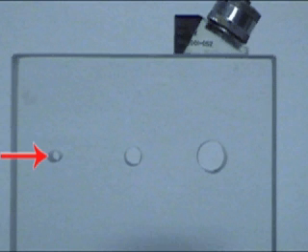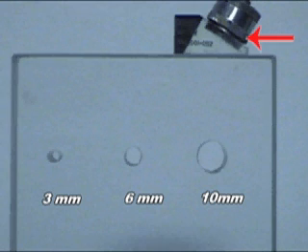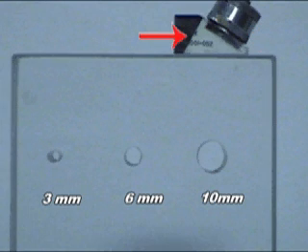A glass block was fabricated with 3 holes drilled in it. These are nominally 10 mm, 6 mm, and 3 mm diameter. An internally spherically focused probe was selected to minimize the off-axis effects. The probe used has a 12.5 mm diameter with a nominal frequency of 7.5 MHz. This compression mode element has a 150 mm radius of curvature. A refracting wedge is used to provide a shear wave beam nominally refracted at about 55 degrees from the normal.